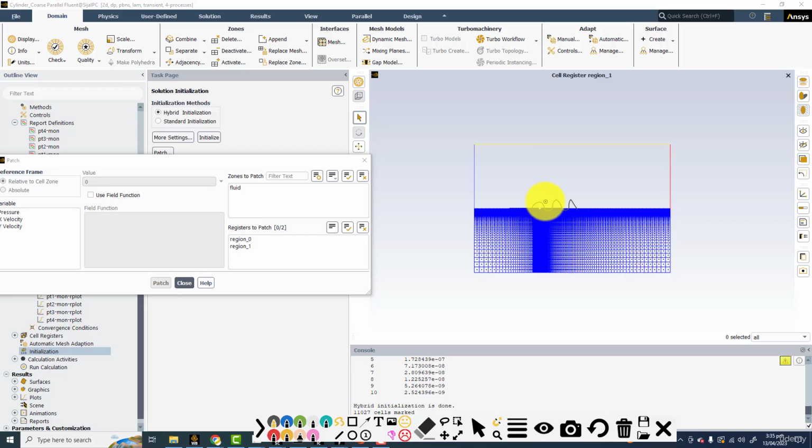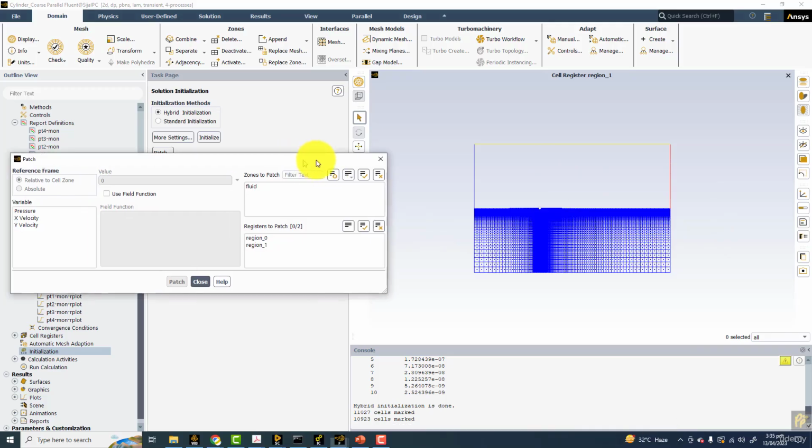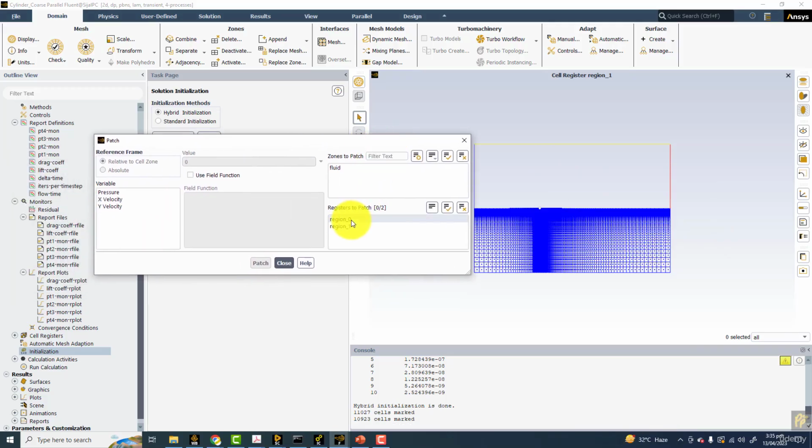The flow will accelerate to reach its unsteady region very quickly if you provide some unbalanced flow field. If you provide an unbalanced flow field, the flow will quickly develop this vortex shedding very easily. So that's why I'm going to provide a flow field that is disturbed.